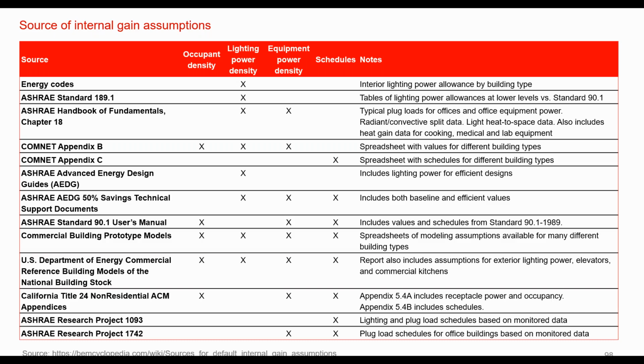Yep, Sam, I would add that the allowable electrical load on the electrical drawing is probably 5 times what the actual load will be. So don't take just what the electrical engineers put on there, because that's not what you're going to see in operation. They might have an allowance of, say, 6 watts a square foot or something. That's a tenant allowance, just on their lease.